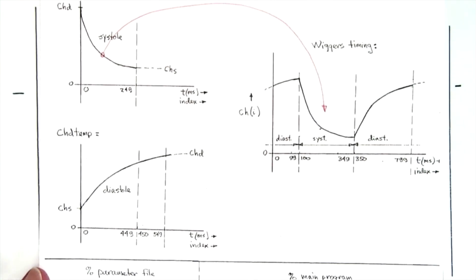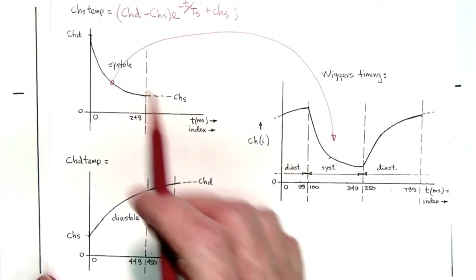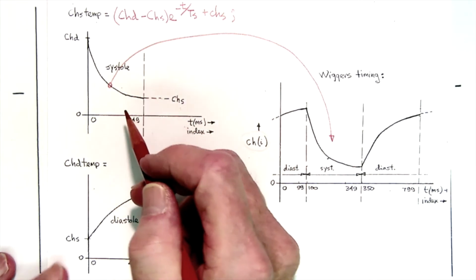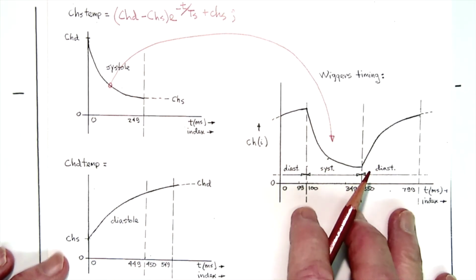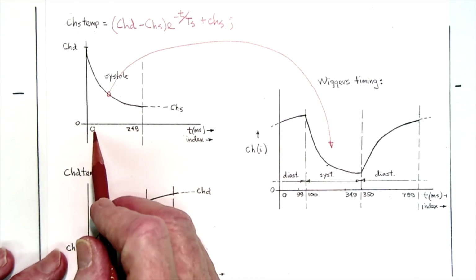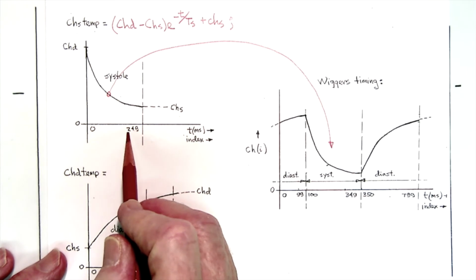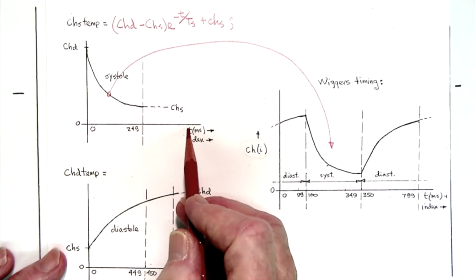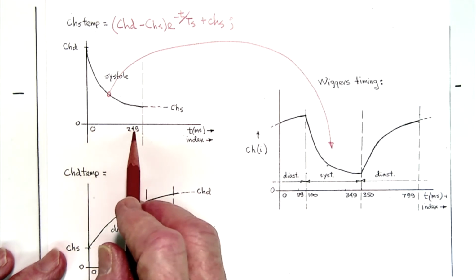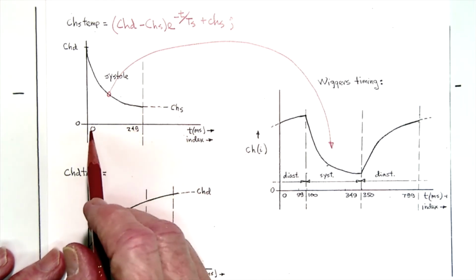Okay, now let's go back and figure out how we're going to cut out this curve that we've just generated with that line in MATLAB. Well, this is going to be a touch tricky because the time vector starts with 0 and ends at 799 out here. We only want the first 250 milliseconds starting from 0.